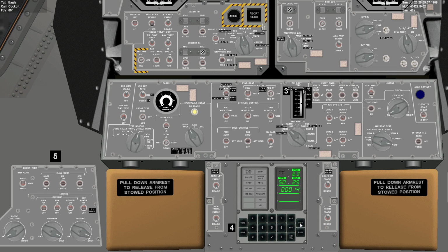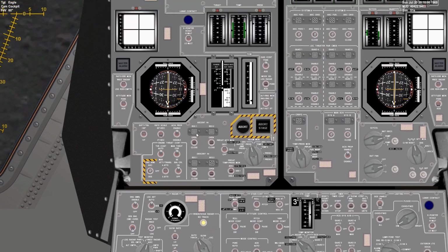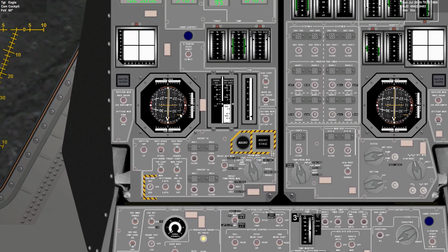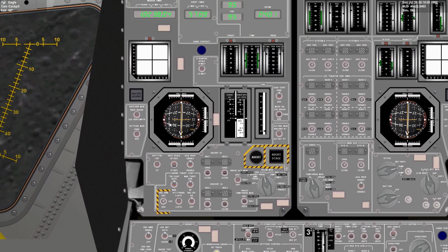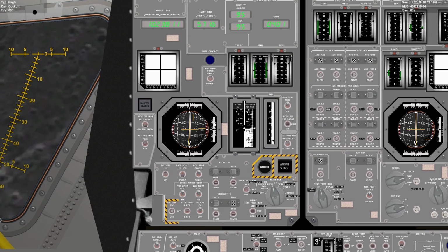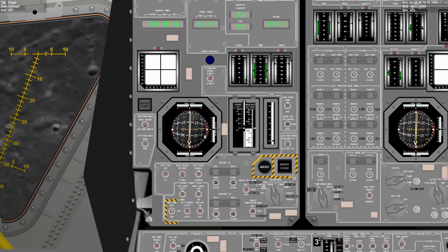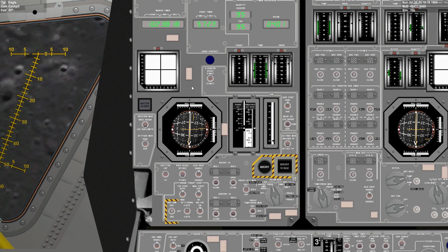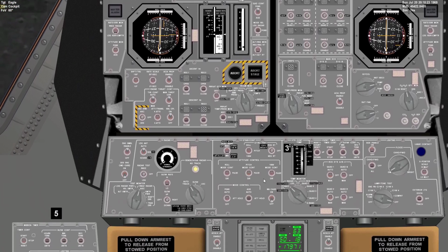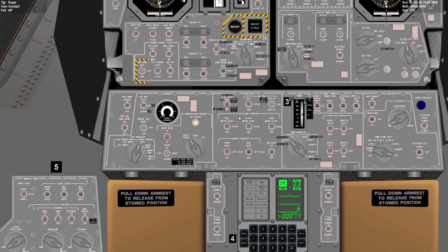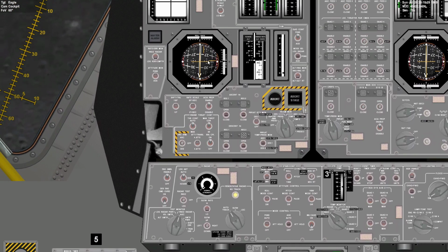It turns out that during descent, those things don't control the IMU or rendezvous radar, but rather the 3 IMU error signals control the FDAI error needles, and the 2 rendezvous radar CDU error counters control the crosshair pointer. So those are taken into account now. You can see the AGC null out its errors here. So we do a final alignment.